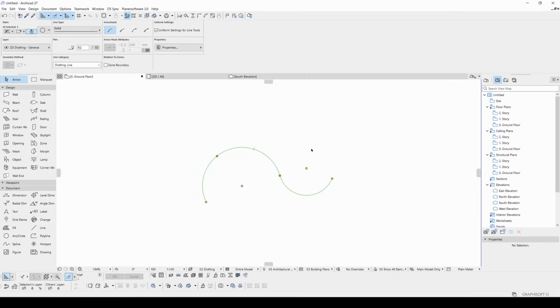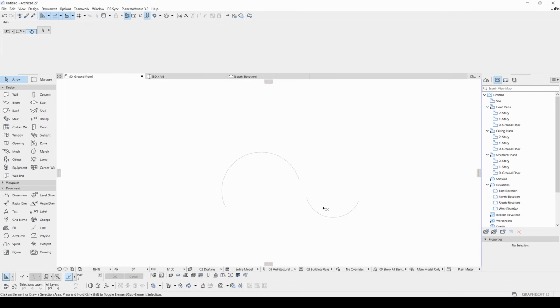Therefore, if we click here on any point of the line, it will select the whole group. With this command, you cannot add points and change. So in order to add points or change points, you will click this suspend groups. From now on, we can continue clicking edges like this, and we can continue editing like this. Let's hit Ctrl+Z to go back.